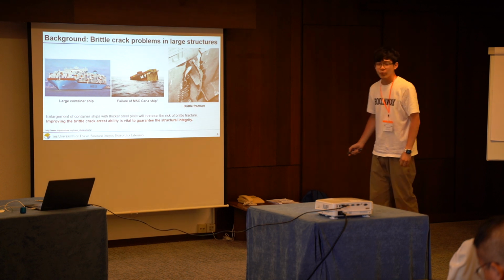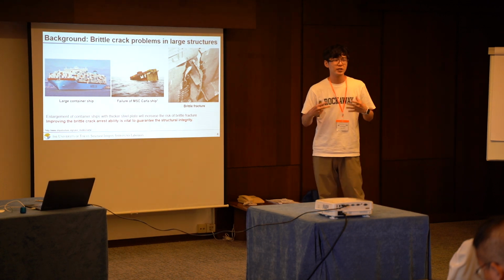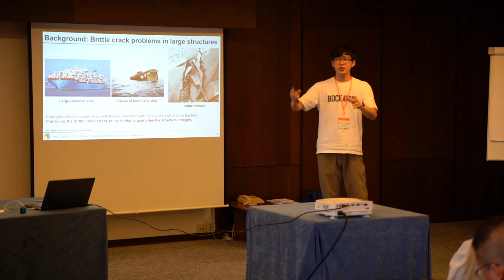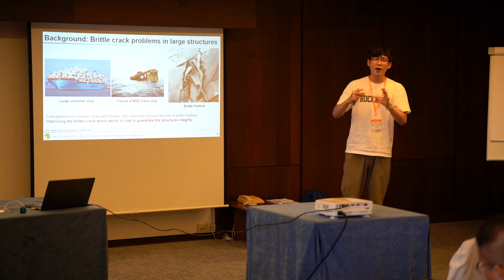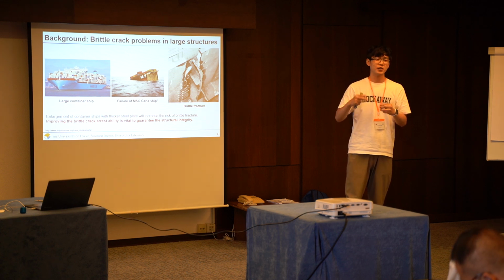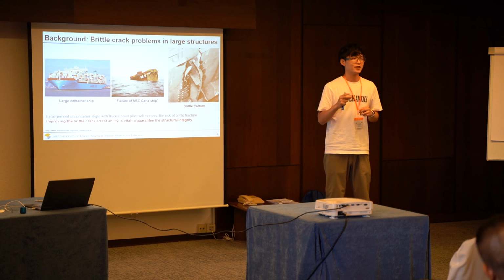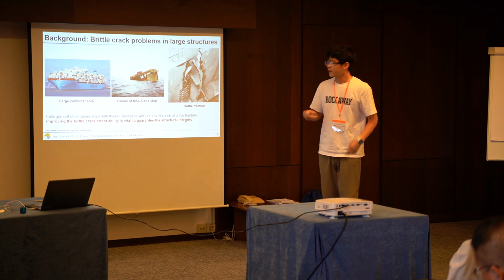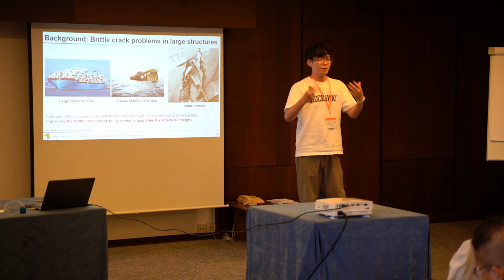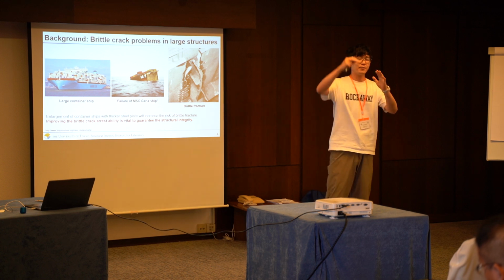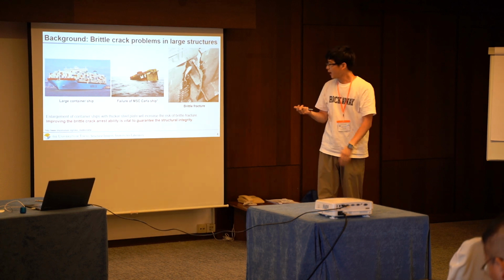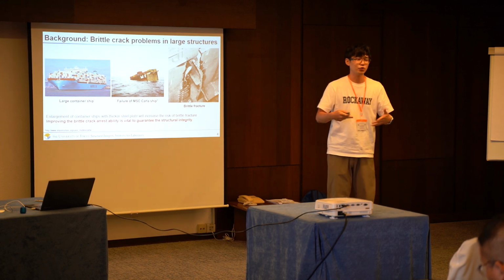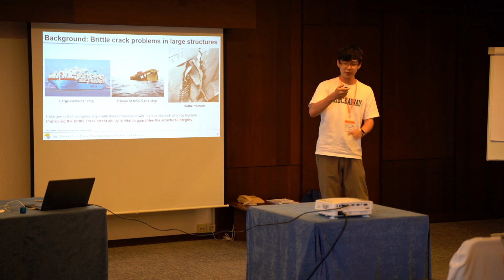With the globalization, the demand for marine transportation is increasing year by year. So the engineers need to use thicker and larger steel structure for building container ships. However, as the size of steel structure increases, the risk of the most dangerous damage, brittle fracture, also increases. So the arrestability becomes very important. The arrestability means the ability to stop the crack propagation. And to clarify the nature of arrestability, we need to develop a numerical method to simulate the crack propagation.